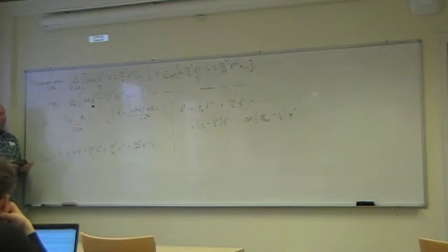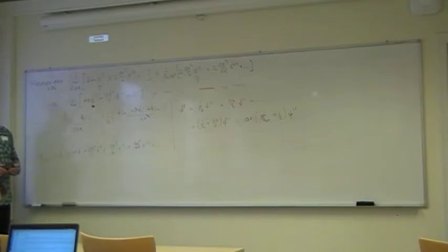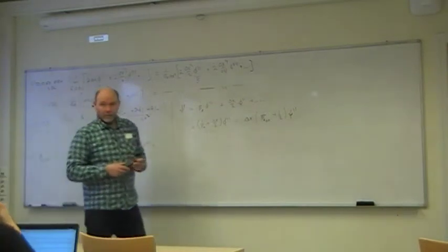So of course nowadays I don't think many use this first order upwind scheme. We'll have a look a little bit later at more advanced upwind schemes. It's not so bad as the first order, but the effect will still be there. You add viscosity into the problem just to smooth things down and get a stable solution. Other questions?